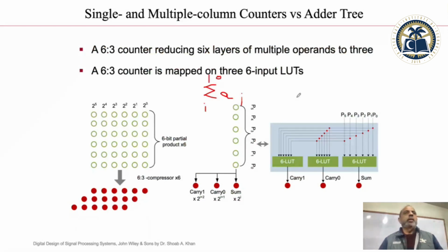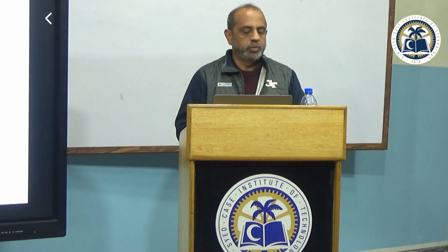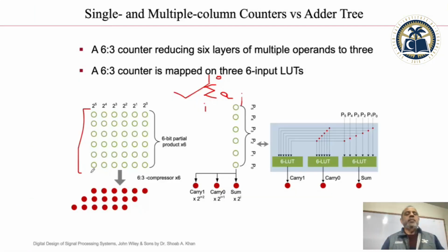So instead of having an adder tree where you add numbers, generate one, then add another, and end up using 9 adders, consuming 9 adders, that is very expensive. Adders are again a very precious resource. We must not waste them. So the best way to do this is to use compression, either a Wallace tree, or, because you are using lookup tables if it is an FPGA, something else people have come up with.